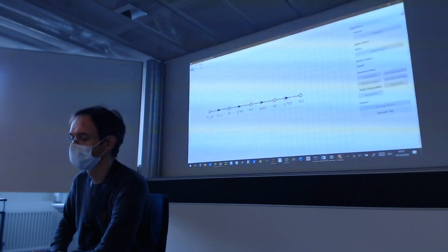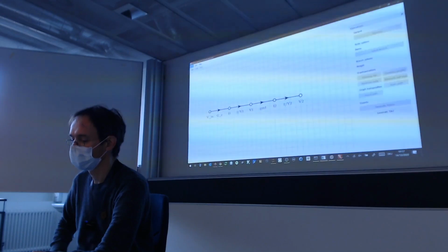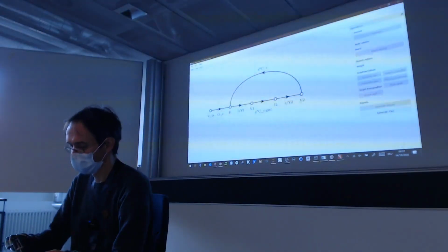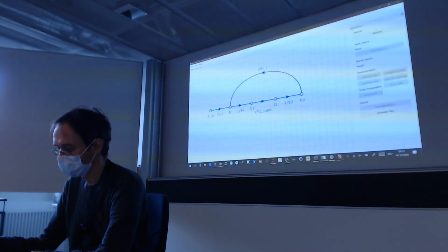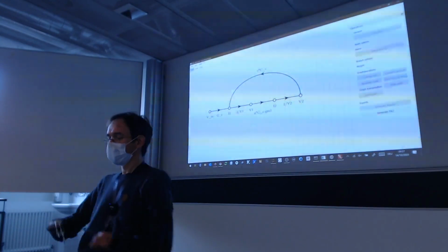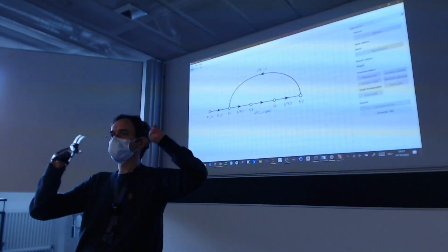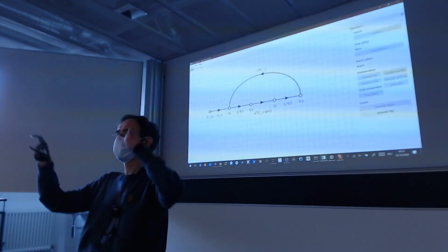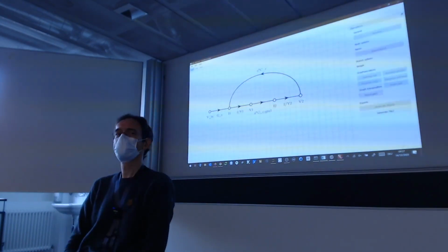And then I included the Miller effect in the common source amplifier. So this is more or less the same thing, but now suddenly I have a feedback, and you saw that the feedback gave the pole splitting. So the poles are moved by the feedback, they are moved apart.